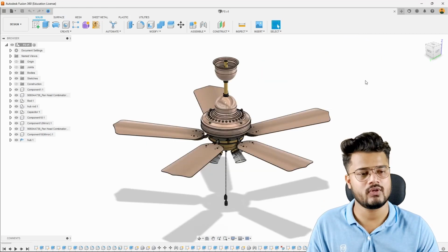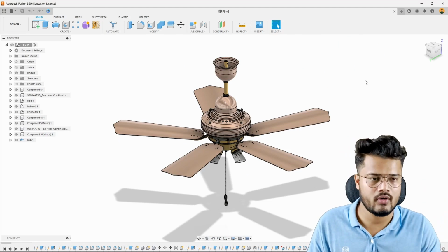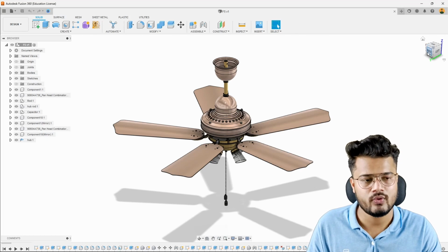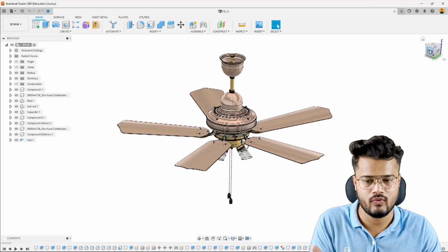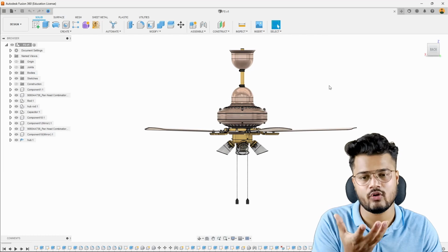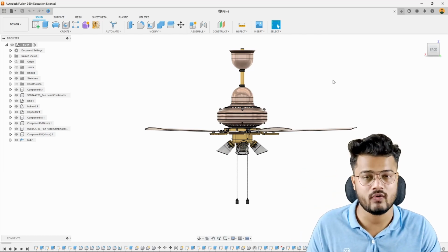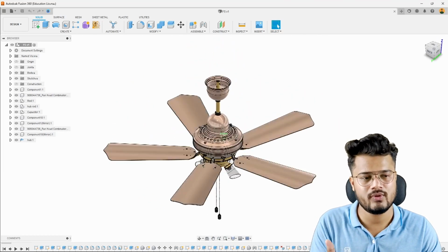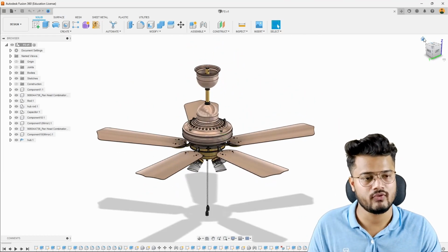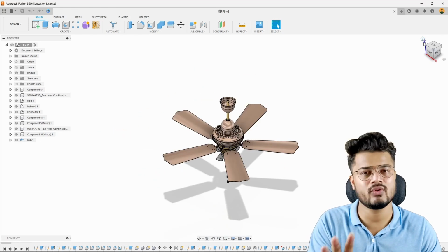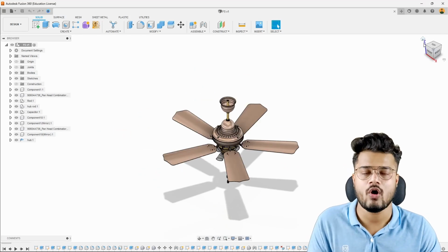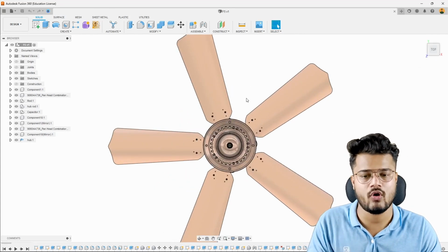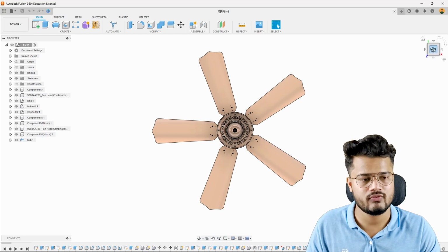You can use it. Next to it, at the right hand top corner, you will see this is a view cube. If you want to get any particular view like back view, you can click here and the design will automatically set according to that view. If you click on it and drag it, it will rotate, so it will help you to navigate. If you click on this home icon, it will set to the default position of any model. If I want to get a top view, just click here and you will get the top view. So like this, you can use the view cube.